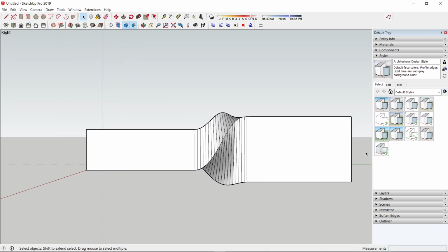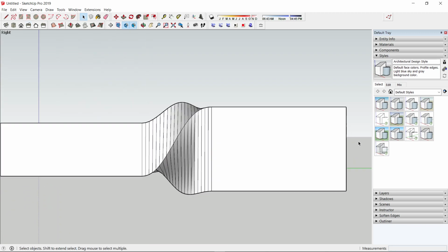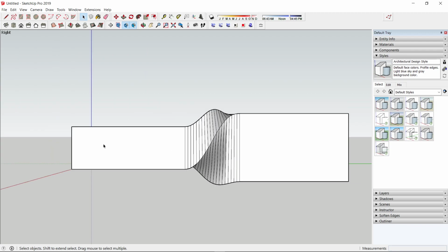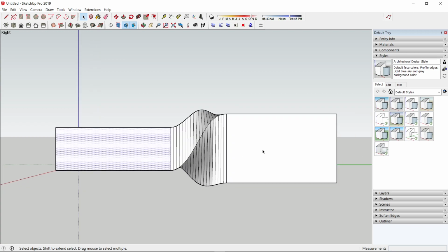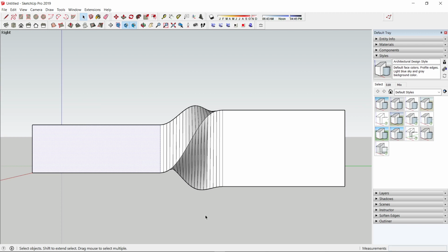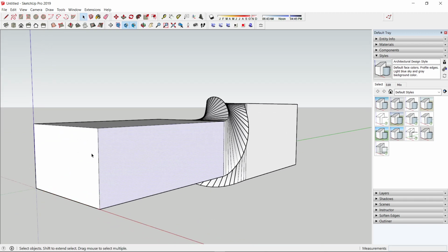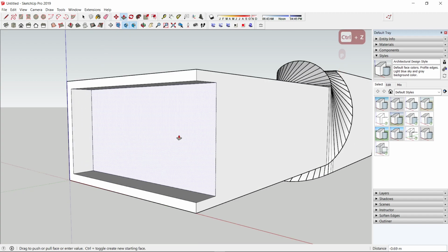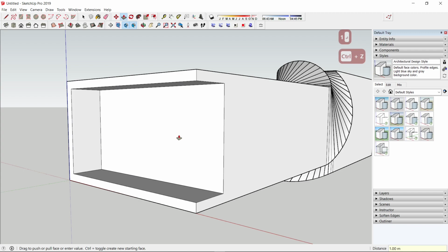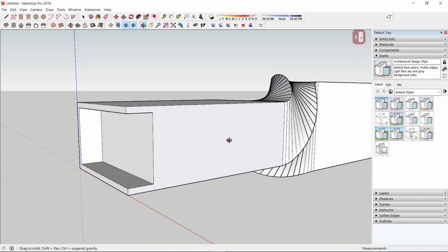And now what is left is to indicate a glass facade on the left side of our model, just to show that there is maybe a living room. And then set our scenes, and then we should be pretty much done with SketchUp. So what I did was just offset it by like 23 centimeter. F is a shortcut for offset, just to indicate a floor slab and a roof slab. Just push it in by like 1 meter. So that'll be like maybe a deck of some sort.